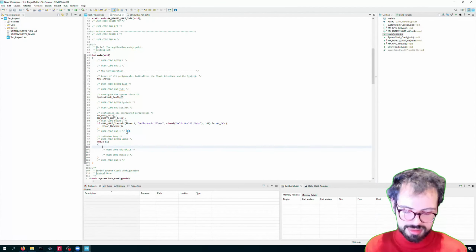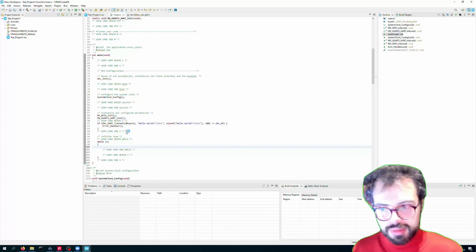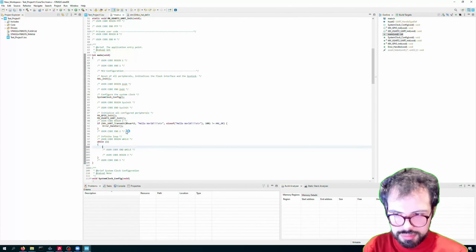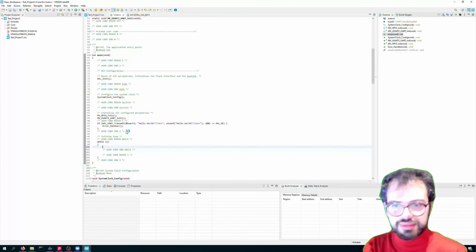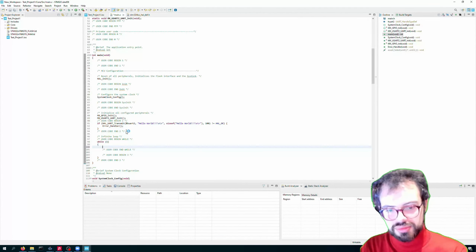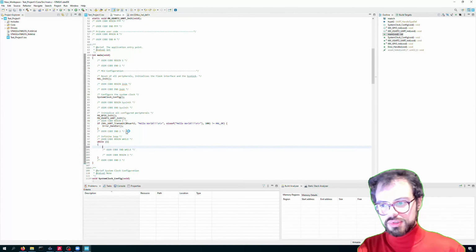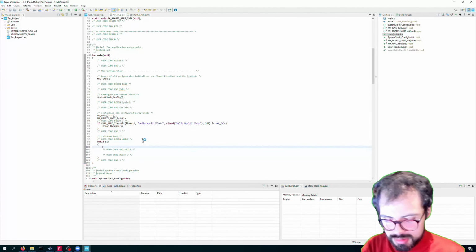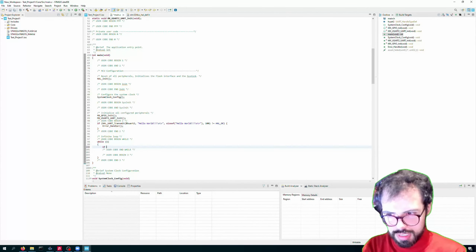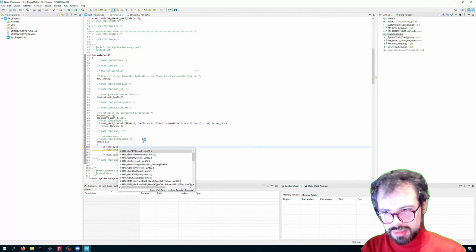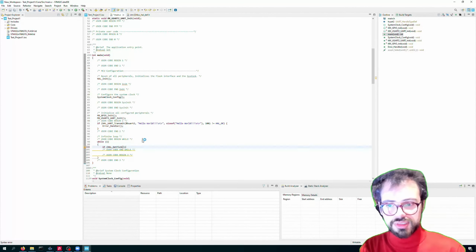We might, for instance, turn the LED on and off. One idea could be to wait a certain amount of time and do the blinking. For that we could go in the while and say, okay, I will write the code very fast, but it's not a problem, I hope. If HAL_GetTick, what is GetTick? It is the internal reference I was speaking about before.